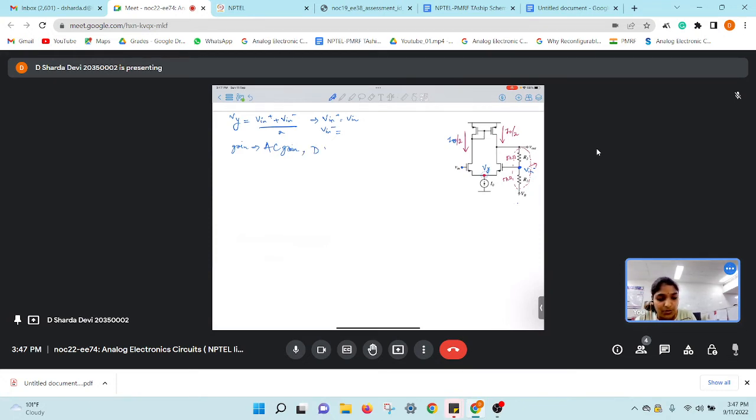We should put DC points to ground. What is VB? VB is a DC bias voltage. That means this VB will be AC grounded.